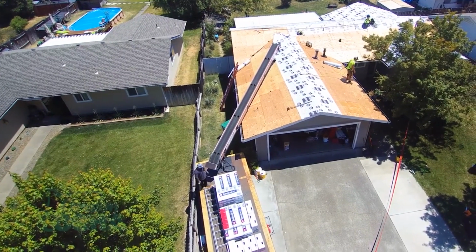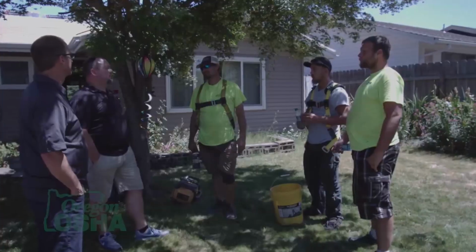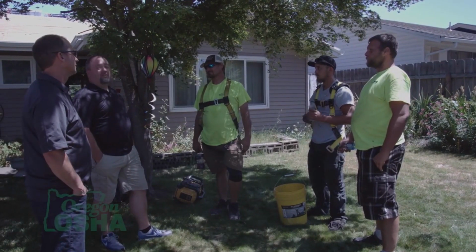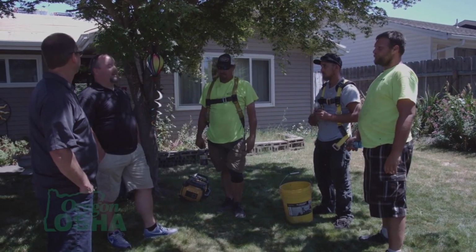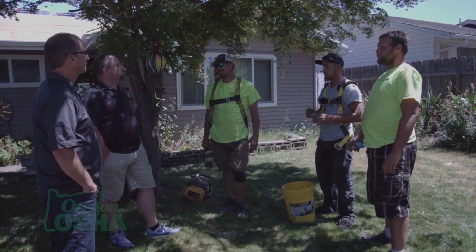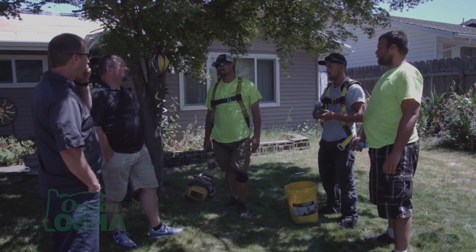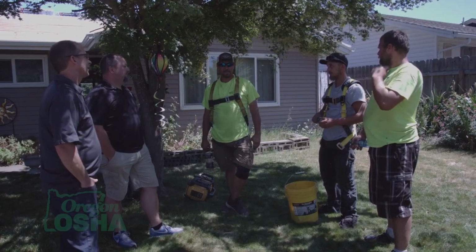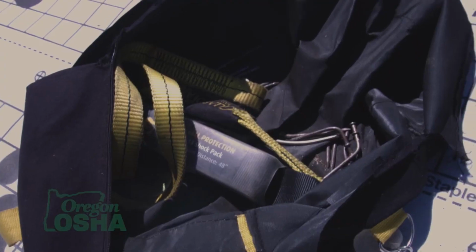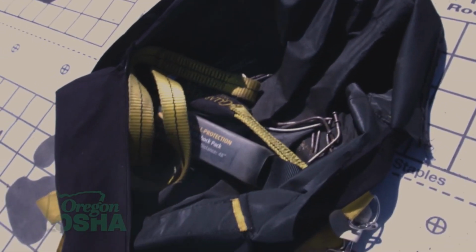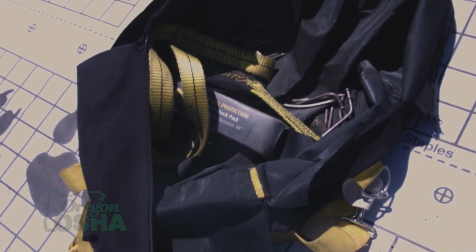And then when we get to the job, to start the job, we will go over that same review again with the crew to make sure they know this is where we want the tie-off points, this is where you need to be a little bit more careful with the public. This is the customer's driveway. We want to make sure their cars get pulled out so that we don't have any chance of hitting anything there. And then setting up with the crew, the foreman has the overall decision if there's something that the estimator might have missed, but we need to have it out there for fall protection, then the foreman gets that taken care of.